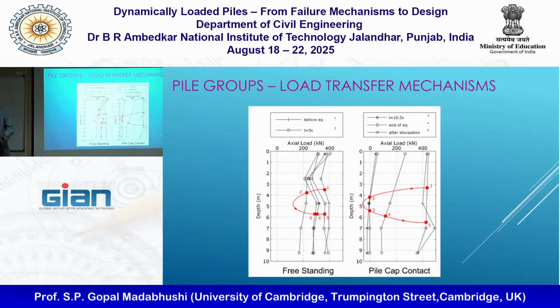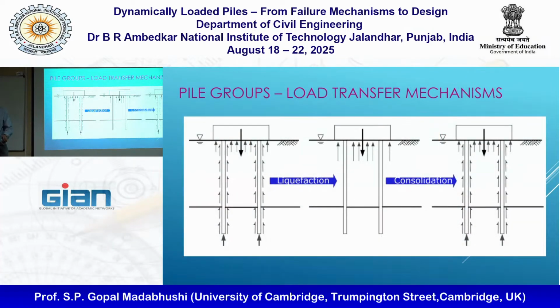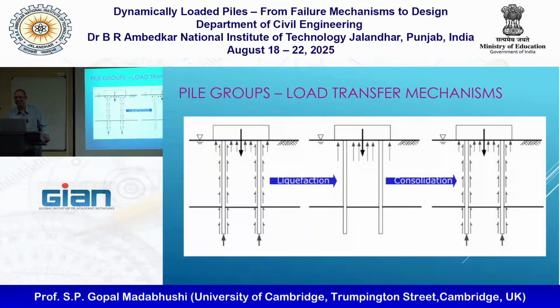But what if it is a reverse case? Like the pile cap resting on the soil. After the first earthquake, the soil is going to sink, along with the pile. Not along with it if the pile is socketed in the rock. In the rock, then, as I said yesterday, the problem becomes a buckling problem.